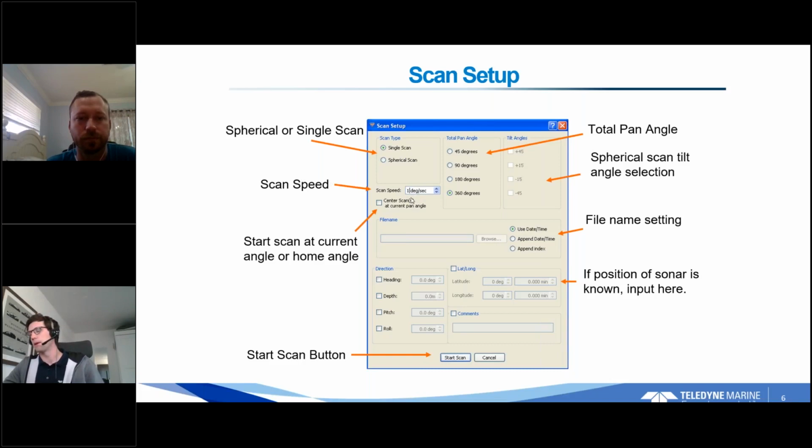Yeah, absolutely. I do use the 10 degree per second occasionally. I mentioned this last week, but I call it a Recon Scan. If you drop the tripod kind of blindly, and don't really see where it's located, you can do a quick 10 degree per second scan to make sure A, your tripod's not falling over, and B, that you're really capturing what you want to capture, whether it's a piling or a key wall or anything like that. So quick scan, 36 seconds if you do a 360 degree. And then that confirms, okay, I'm in a good location. Let's slow it down to 2 degrees per second and do a higher accuracy or higher data density scan by slowing it down.